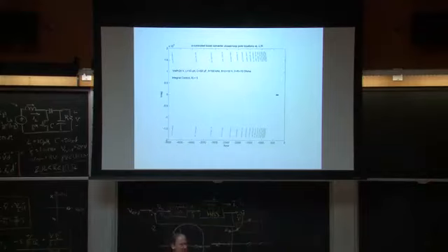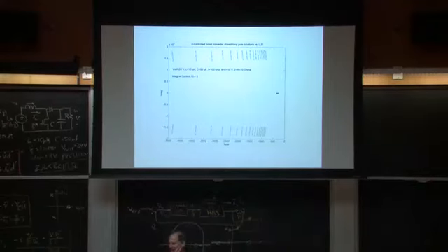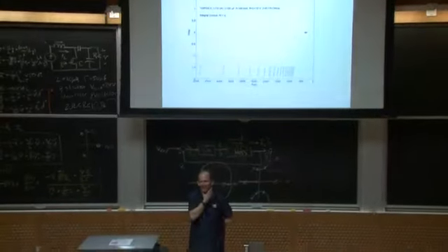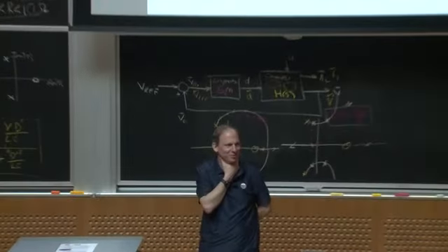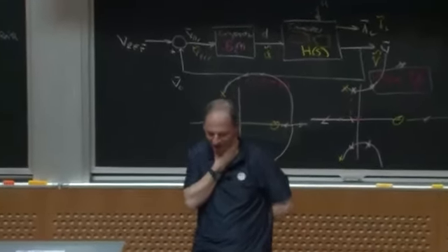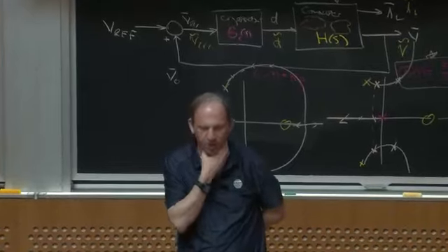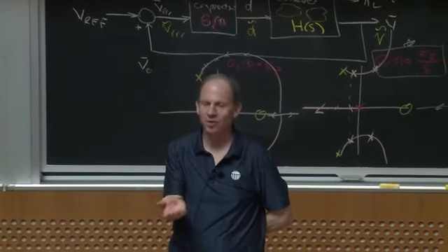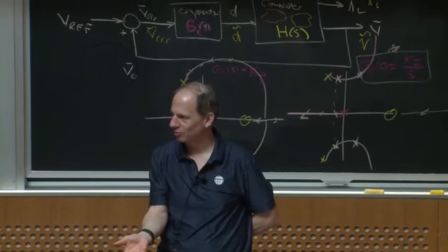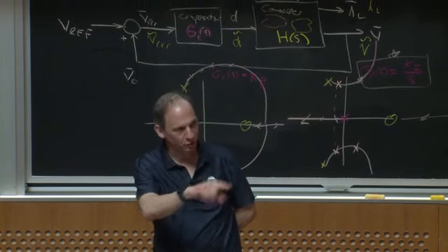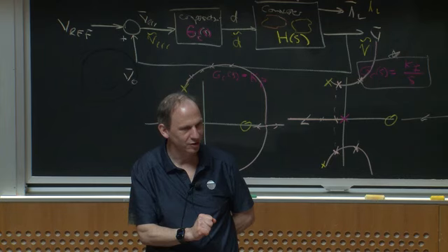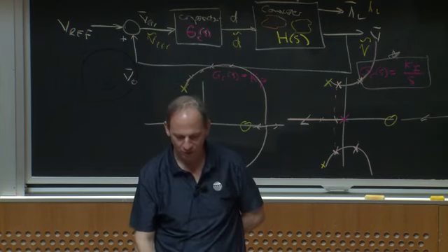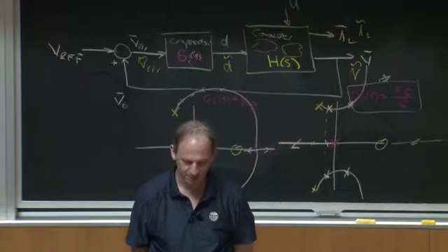how stable is it? And this is where me and your average control textbook break paths in terms of what we're happy with, okay? A typical measure for those who do control are things like the phase margin you have or the gain margin you have on your loop, right? So what you do is you look at the loop gain and you plot that out, and you can look at the open loop gain with a controller. This is what it looks like.